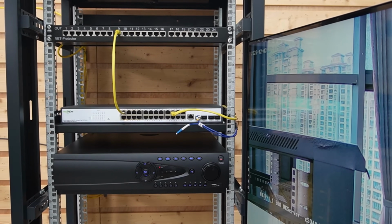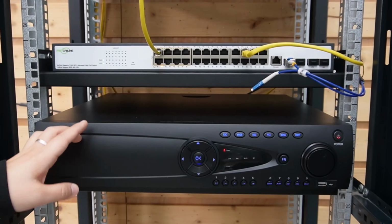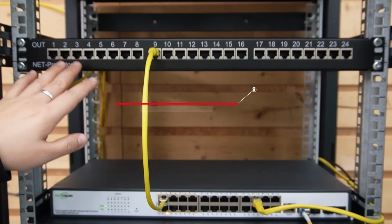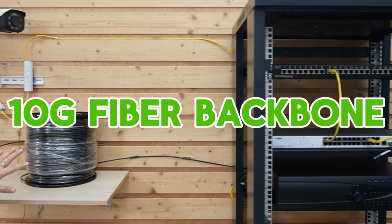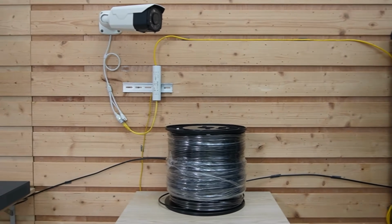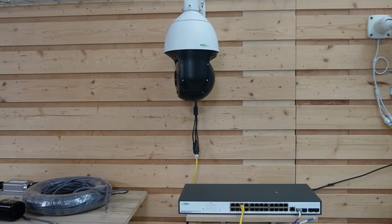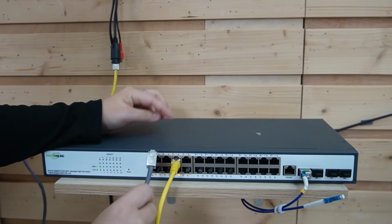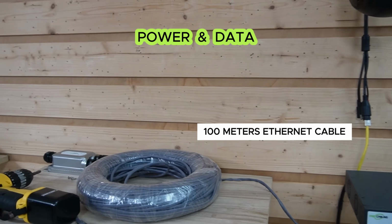So now let's look at our full setup. Inside the main building, all the camera recording happens on an NVR. That NVR is already plugged into our 480 watt PoE++ switch, along with the indoor surge protector in the rack. From there, we jump onto a 10G fiber out to another 480 watt PoE++ switch. And from this field switch, we are going to run 100 meters of copper to our extender. So let's plug it into the PoE++ port so we can send both power and data.